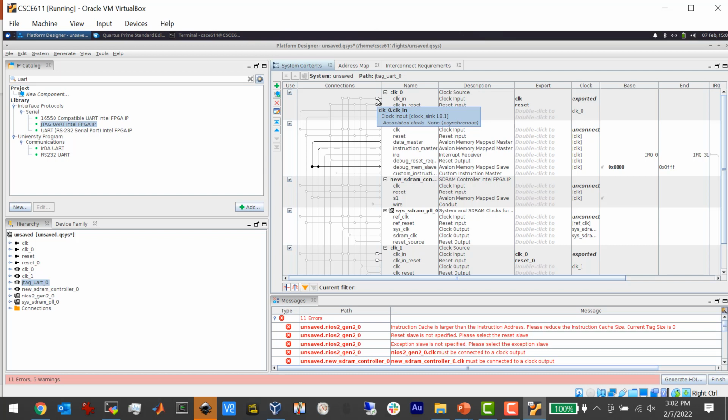So this is how we're going to clock the whole system. The clock's going to come in here, but we have to run it to the phase lock loop because this is only a reference clock and the phase lock loop is what's going to provide our actual clock. Now you might say, why not just use that as your clock? You can, but then you can't change the speed. But we're not going to change the speed anyway. But it's also a messy clock. It's coming off of a piezoelectric crystal. It's not a good clock signal. It's dirty, it's noisy. We want to clean it up, so we use this phase lock loop to make it into a cleaner signal.